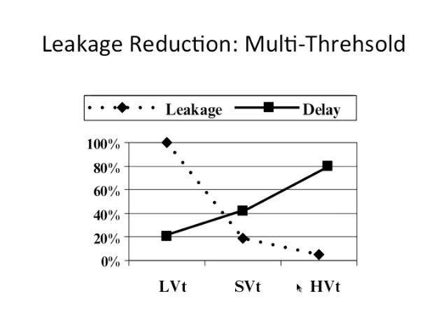So here, for example, you have three different threshold voltages for transistors: low threshold, medium threshold, high threshold, and the leakages can vary dramatically between the high and low, and you can have quite a bit of change in the delay also. So you see this is clearly a trade-off between delay and leakage power, and so as a designer you have to decide where you want to be.